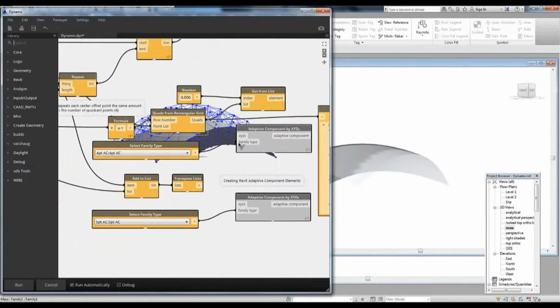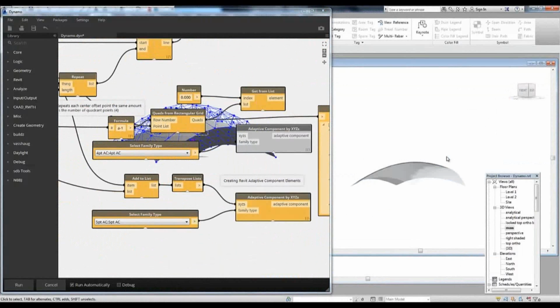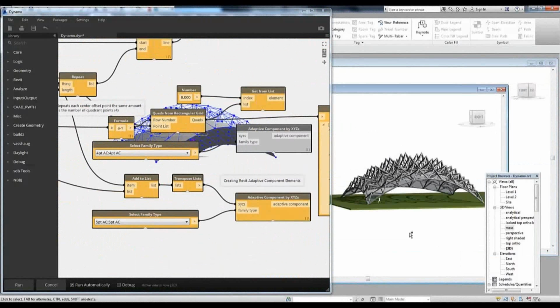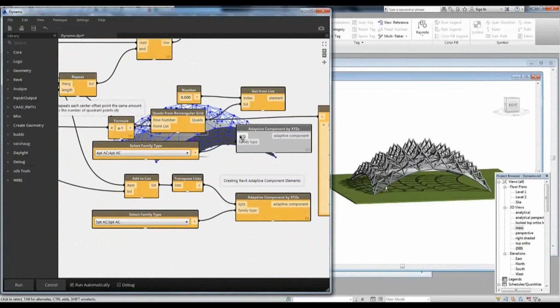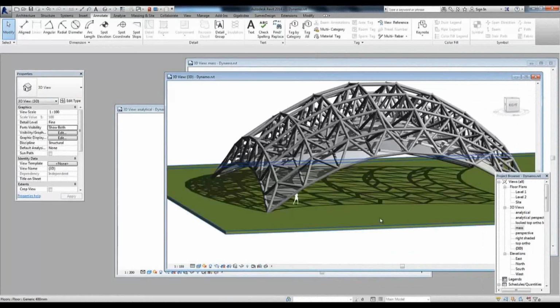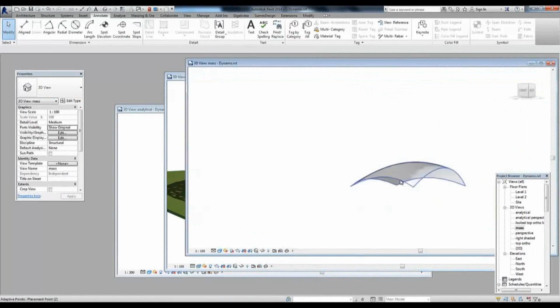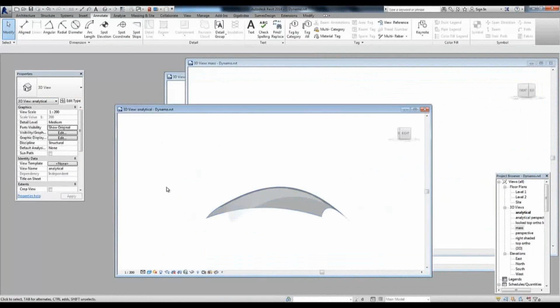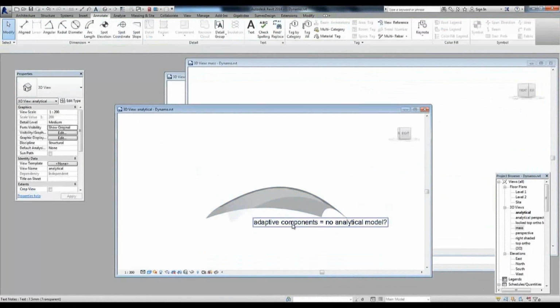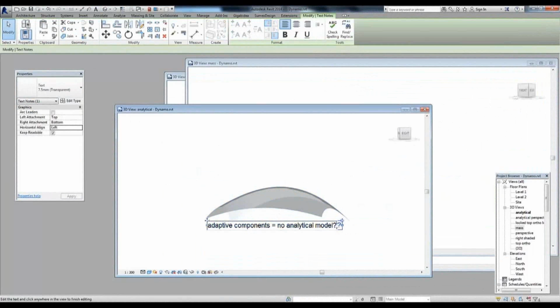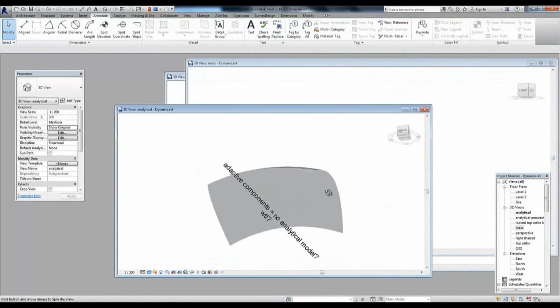So one of the problems we have in Revit is that you can make something look very detailed and well connected, work on the fittings and connections there, using things like adaptive components to make it look like welded tube steel, or you can make something that is of structural objects that are tightly connected and know what they are and can be analyzed. And there's this idea of an analytical model in the structural world that is important when you're trying to run it through analysis applications.